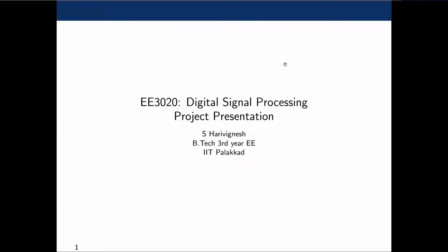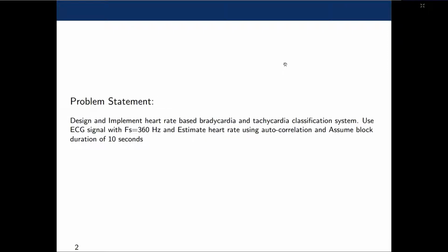In this video, I am going to be presenting my project in the Digital Signal Processing course. The problem statement is to design and implement a heart rate based bradycardia and tachycardia classification system. Use ECG signal with fs equals 360 Hz and estimate heart rate using autocorrelation and assume block duration of 10 seconds.